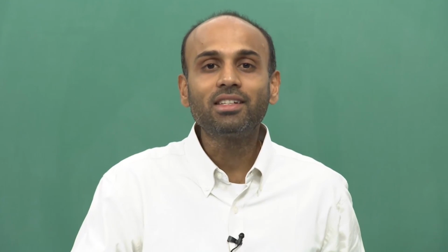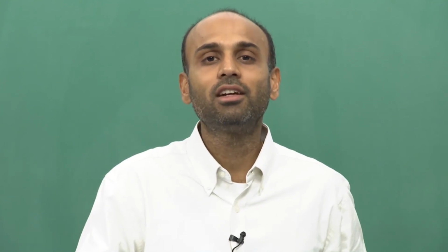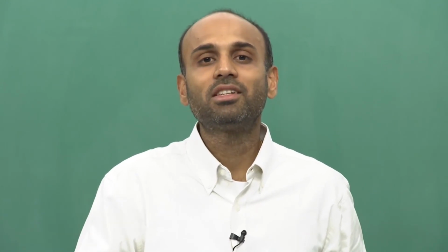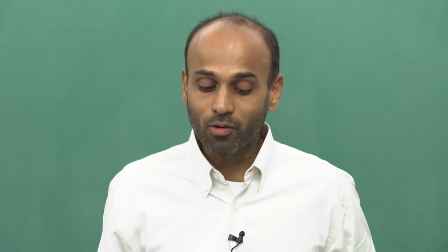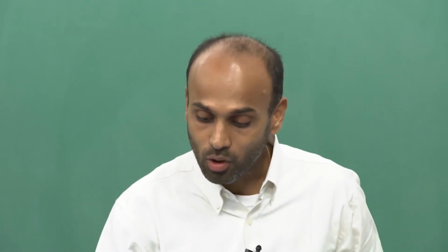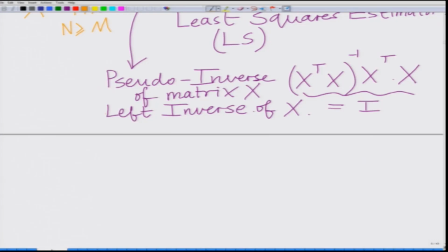And what is interesting is that in the high signal to noise power ratio, this MMSE estimator again reduces to the least squares estimator, that is the maximum likelihood estimator. What is also interesting is what happens in low signal to noise power ratio. In low SNR,